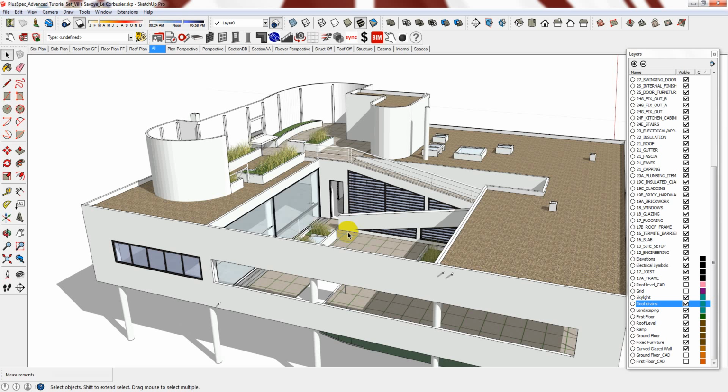The second scene type are scenes that you will use for presentation or 2D documentation purposes, such as perspectives, elevations, plans, and sections. The good news is that Plusspec has automated the majority of standard scene types for you and has also categorized them into different scene sets, for example, designing or estimation. However, you need to have a thorough understanding of how scenes work so that you can control your modeling workflow as well as your presentation and 2D output. Although Plusspec automates the standard scene types for you, you will want to modify them and create new ones.